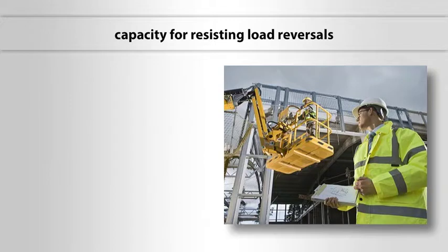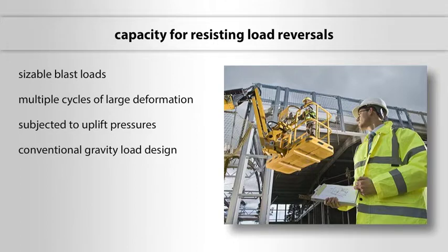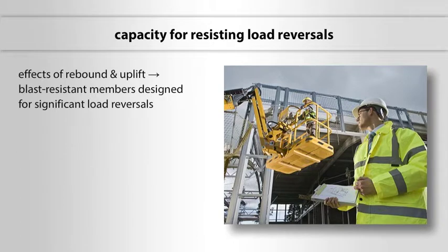Capacity for resisting load reversals. In response to sizable blast loads, structural elements may undergo multiple cycles of large deformation. Similarly, some structural elements may be subjected to uplift pressures, which oppose conventional gravity load design. The effects of rebound and uplift, therefore, require blast-resistant members to be designed for significant load reversals.